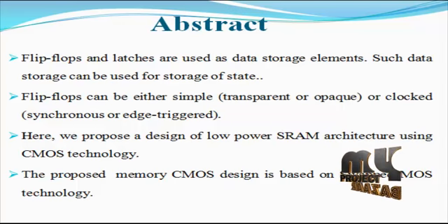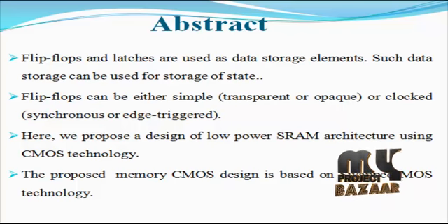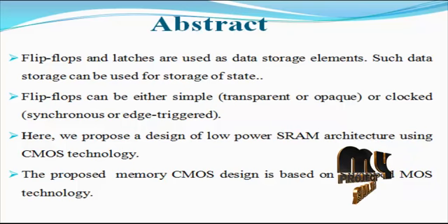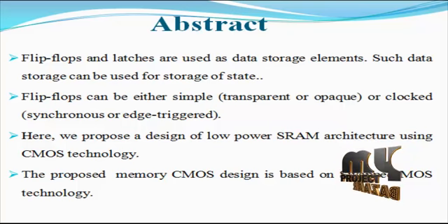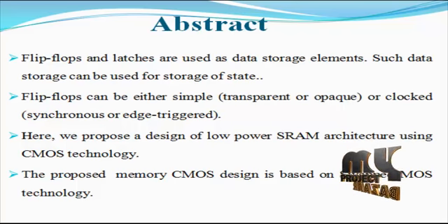In this paper, a new approach towards the design of a memristor based non-volatile static random access memory cell, using a combination of memristor and metal oxide semiconductor devices, is proposed. Memristor and MOSFETs of Taiwan Semiconductor Manufacturing based on 180 nanometer technology are used in the form of a single cell.